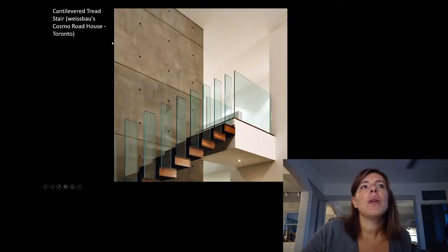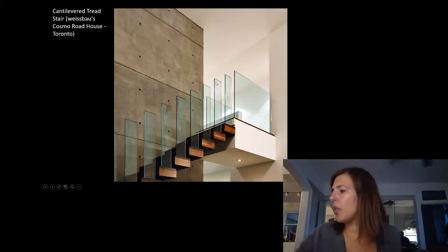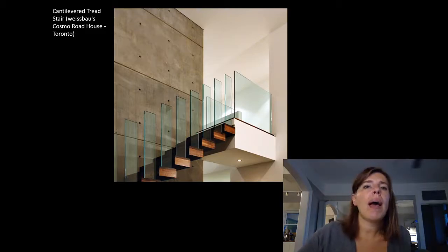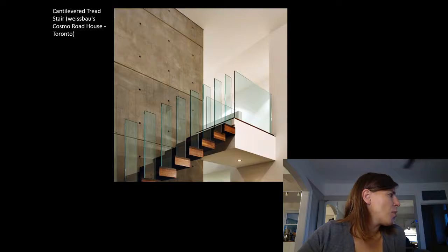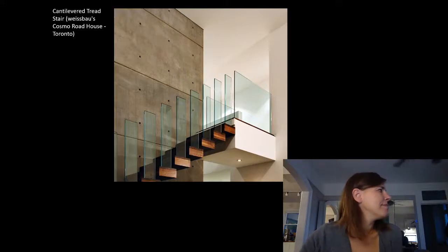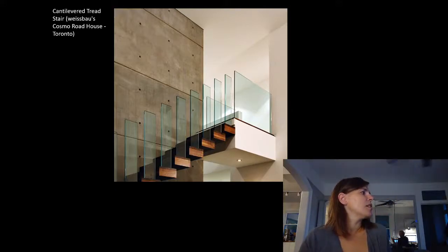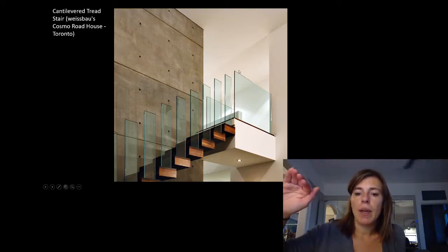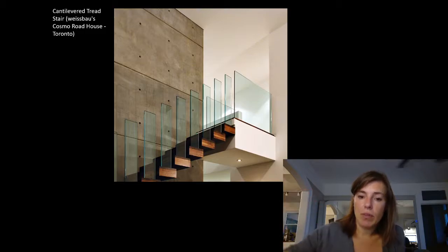This is the one that Dave showed you that he did with Kevin Weiss, a local Toronto architect. So one of the other things is, like we talked about, the continuous top rail. How did Kevin get away without the continuous top rail on this stair? Roll the dice. Also, the width of one light failing: the width of the opening was small. So the top rail is about if a panel fails, you don't have a big, huge opening.